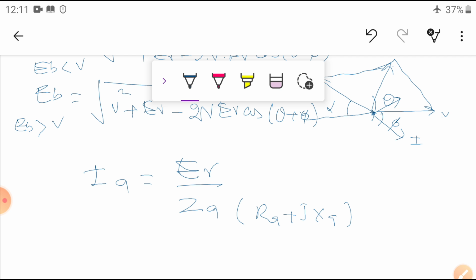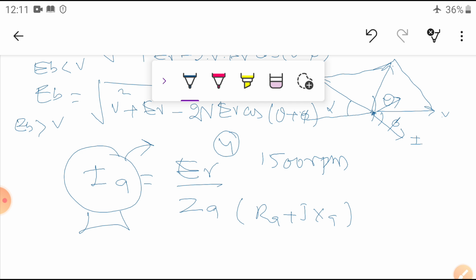Now what is happening in this? How will the armature current change if the load increases on this? As you know, the synchronous motor runs at synchronous speed only. That means, suppose a 4-pole machine, it runs at 1500 RPM only, otherwise 0 RPM. Not at 1200 RPM or 1000 RPM, because it is just like the binary case, whether it is 0 or 1 only, not analog.